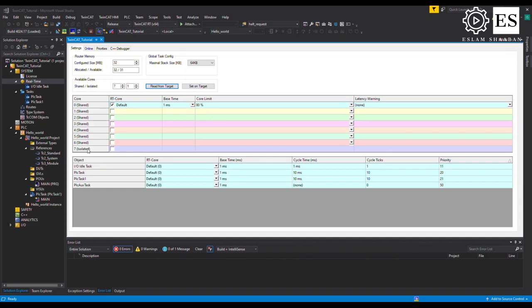The 7th core is isolated, which means it's 100% dedicated to executing the TwinCAT tasks. And I have found that mixing Windows and TwinCAT 3 on the same core might cause problems. So if you have a machine with more than one core, I totally recommend allocating at least one isolated core for TwinCAT.